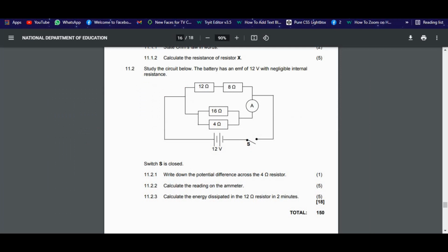Why does this make sense? A number of reasons. One, look where the ammeter is situated. Current splits in a parallel branch. We have everything that we need because we have the resistance values of both resistors and the potential difference across both, because it's a parallel branch. So we can easily calculate the current going through each of them respectively and add them together, because current splits in a parallel branch, meaning that it must split and rejoin.